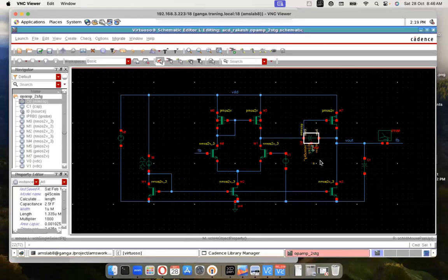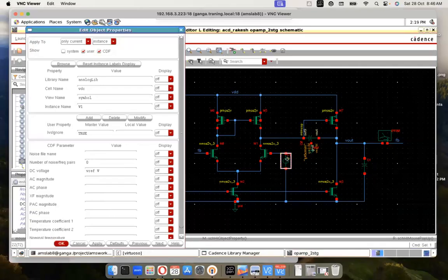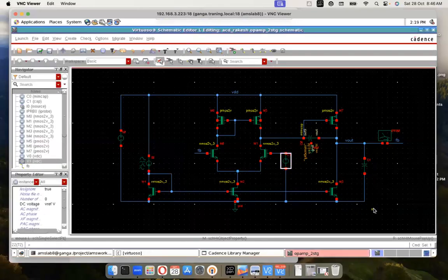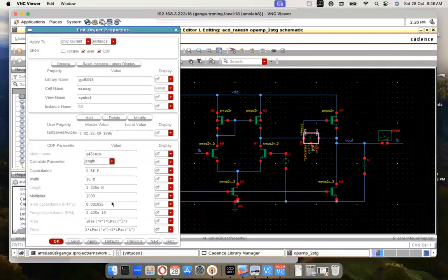Okay, I just put it. What else I have done? I have given a reference voltage. Yeah. I have a question. This capacitance again, in reality it will be a length and width of the MOS. Correct. It need not be MOS. It is not always MOS. This is MIM cap. I'll give you a brief intro of what MIM cap is in a while. But yeah, in reality, it will be some dimensions of some device or some metal or anything like that.